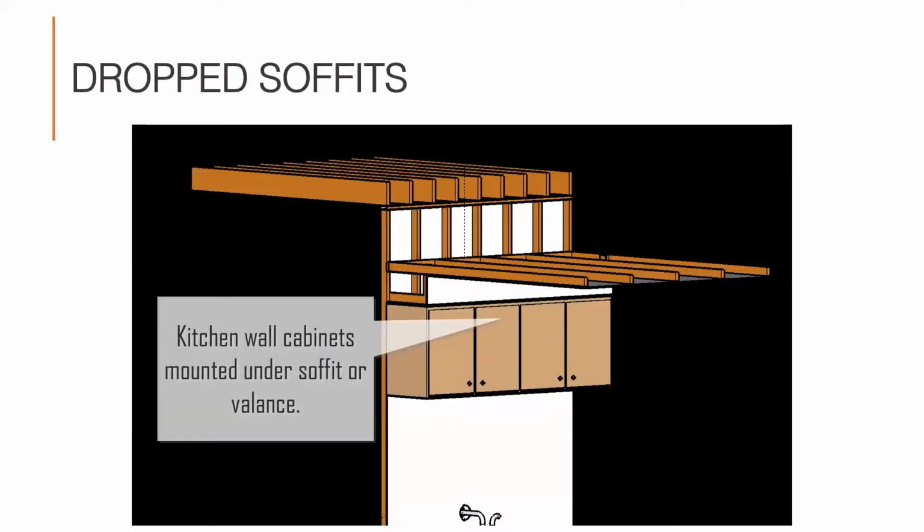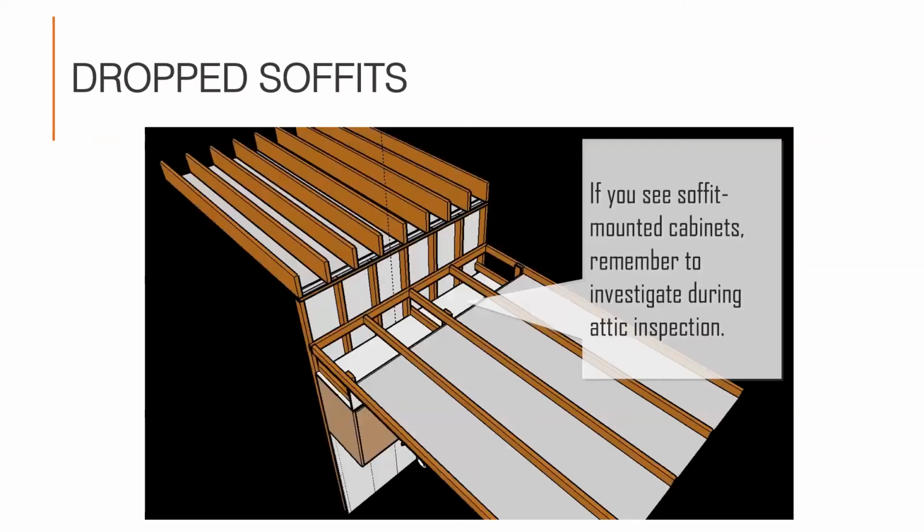This drawing shows a change in ceiling height and a drop soffit, another common culprit, which creates two causes for the breakdown. Even without a change in ceiling height, drop soffits cause misalignment in the pressure and thermal boundaries. The pressure boundary, which is the sheetrock, drops below the level of the attic floor and is not typically sealed at the top, which again creates a void in the insulation and allows air to move freely in and out of the stud bay.